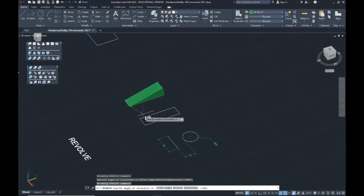So it's taking that simple rectangle we started with, and the more degrees it spins around in a circle, the more of a full cylinder you're going to get. You never have to revolve a full circle. There are 360 degrees in a full circle, but you never have to go the full 360. You can make this a small piece of pie. You could make it half of a pie by typing in 180, or 3/4 of a pie by typing in 270. I'm going to start by doing the full circle, so I'm going to type in 360 and hit enter.